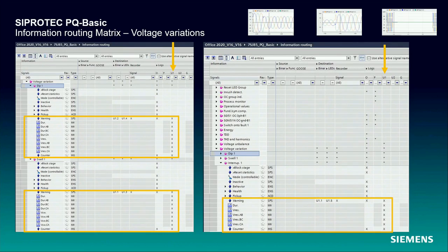The next information is the voltage residual, that is the worst measured value during this event. The extreme value for each separate phase is listed below. And finally, the counter voltage value will be increased by each newly detected voltage dip. An equal amount of information is provided for voltage swell and voltage interruption on the bottom and on the right side of the screenshot.